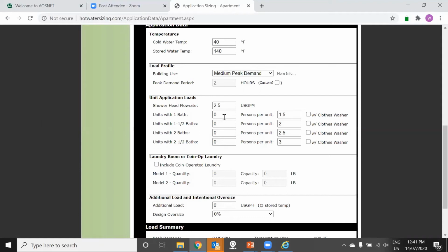And with tankless, we always aim to circulate between 2 and 4 gallons per minute. Anything less than 2 gallons a minute can produce air bubbles, and anything over 4 gallons a minute can produce turbulence and erosion of the core heat exchangers, as well as your pipes. So that's our target in there.